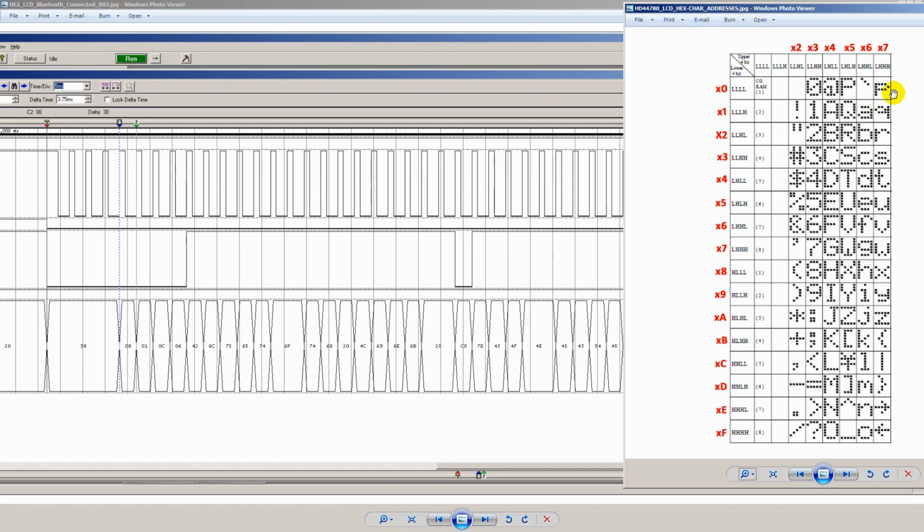And so you just go and map out which characters you want to have displayed, and you assign that specific hexadecimal value within the VHDL code, and that will dictate which character is being displayed. Eventually, there are areas of memory within the RAM where you can send your own character data and pixel information, so you can create your own graphics or custom characters. That'll be a future instructional video that I'll put together to show you how to do that.